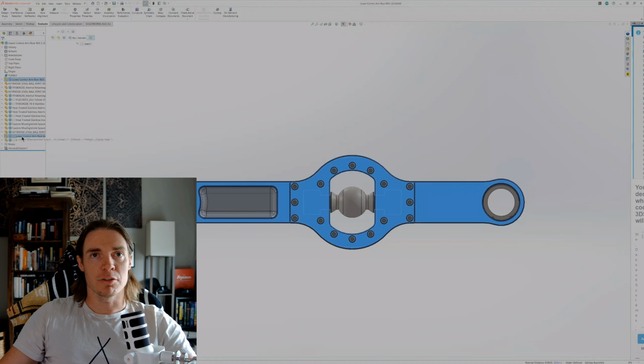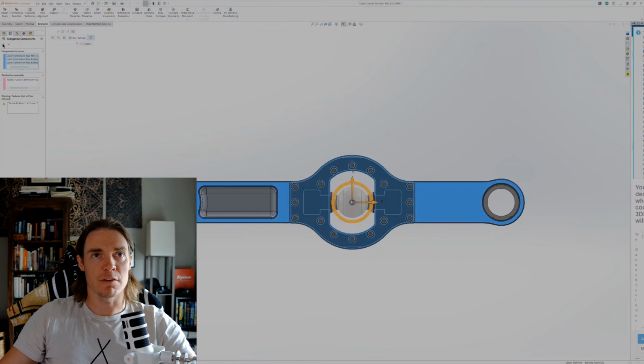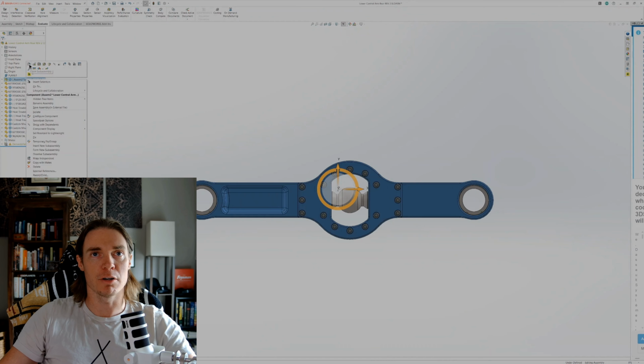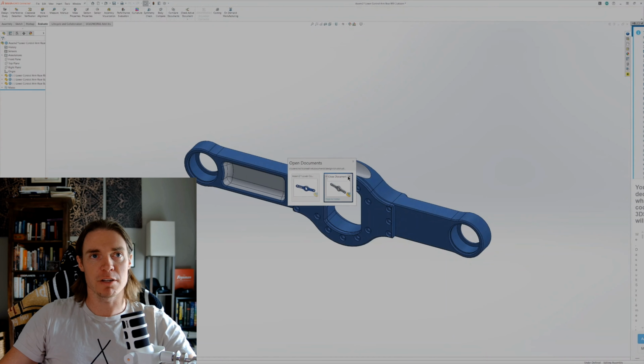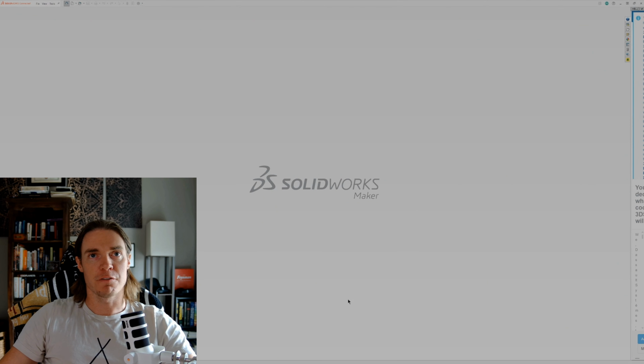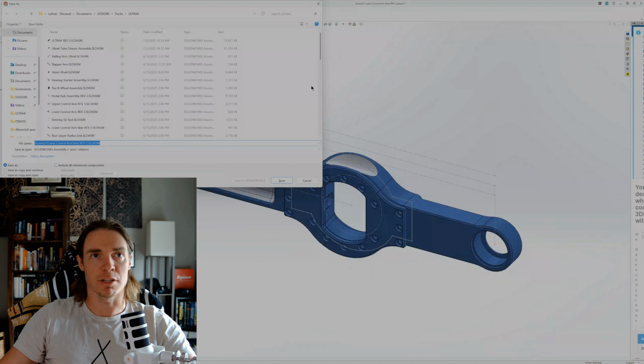What's a lot easier is to take the parts that you need to save and save them as a new part file and then import that entire body into SimScale. So now I have these 2 parts in the assembly. I'm going to save that assembly as a part and rename it FEA and make sure I don't use it anywhere else. The first time I did this, it defaulted to only saving the surfaces, and that doesn't quite work because you need to save as a body.